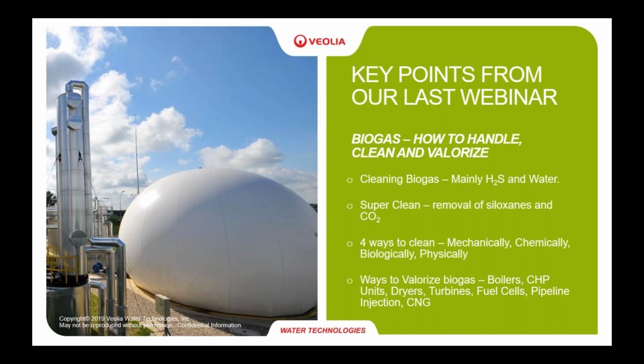We talked about cleaning biogas, and when we said cleaning, we really were emphasizing the removal of hydrogen sulfide and water. Unless you wanted to get the gas super clean, in which case you had to get rid of the siloxanes and the carbon dioxide in the gas also. And we discussed the four main ways of cleaning gas, which was mechanically, chemically, biologically, or physically.